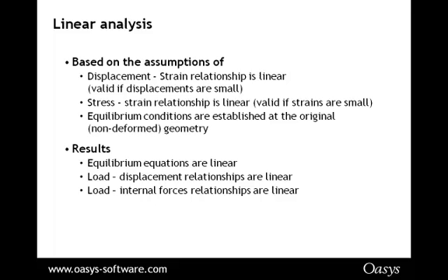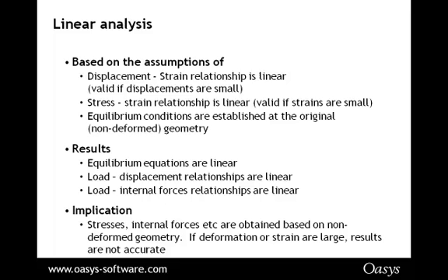This means that if you want to go from an individual load case to an ultimate limit state case, you can just multiply the results by the ULS factor and be happy that the results will be okay. But the thing to remember is if your deflections and your strains are large in the model, the linear analysis won't necessarily be appropriate or accurate.